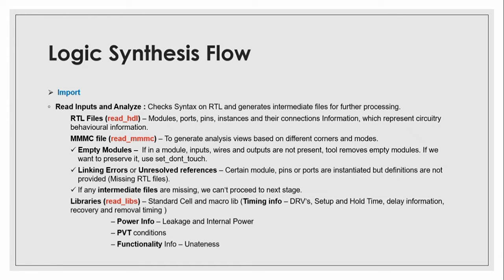Then setup and hold time, delay information, recovery and removal timing, all this information will be given there. Then power-related information like leakage and internal power will be given there. PVT conditions will be mentioned there. Also the functionality information like unateness, which we already discussed.